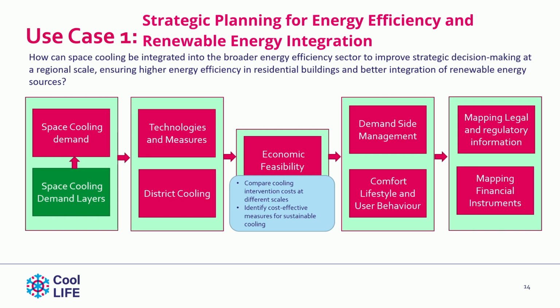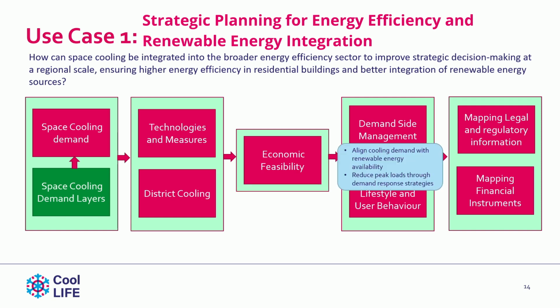And then we look into the demand side management calculation module, which allows us to align cooling demand with renewable energy availability and reduce peak loads through demand response strategies, and also look into the possibility of introducing PV modules into supplying the cooling demand, supporting the integration of renewable energy.